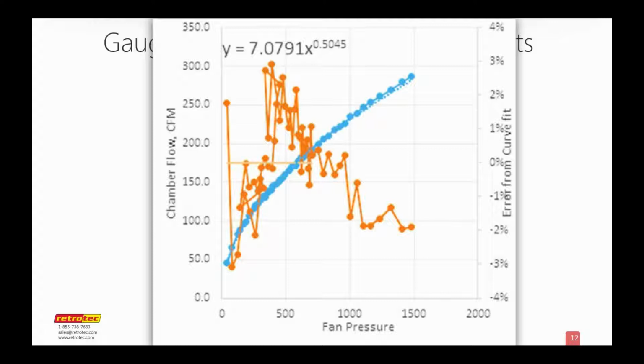It's physically impossible. But if you read the manual carefully, as some people do, almost no one does, it says in the duct blaster manual that the back pressure, the pressure that the fan is seeing, must not exceed 100 pascals. And the reason for that is that an axial fan doesn't really like pressure all that much. It's really designed for high flow rates.